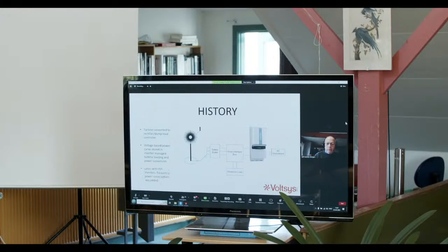More recently, a frequency-based power curve more accurately reflects the speed of the turbine and the amount of power available. So based on the frequency of the wild AC coming from the turbine, the inverter converted that amount of power and in turn applied that as torque to the shaft of the generator.